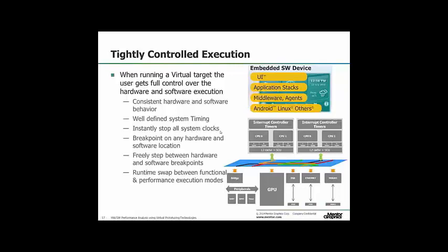We also have things like semi-hosting facilities, so you can write and control the hardware without having to rely on perhaps a UART console to get some debug messages out. You can just use a semi-hosting call to output a message without having to use some kind of UART. So it gives lots more chance to debug and develop software, and it's a nicer way to do that.